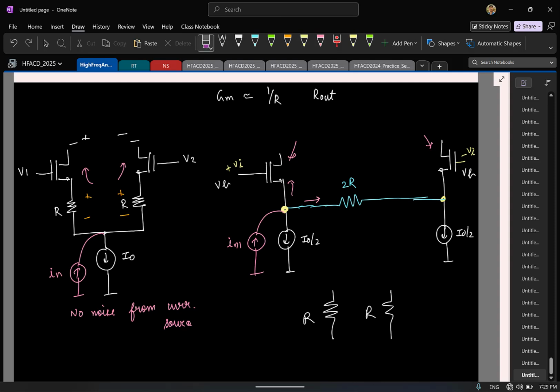How are you planning to merge it? Yeah, but if you do this, then the resistor is not in. This is sort of shorted, right? Maybe you can think of some different variant, but yeah, it's not straightforward. So that is a disadvantage. So even this noise current, I mean this current source that will be injecting noise, that will also not get cancelled. So that is a downside to this technique, that you will have additional current due to noise sources.